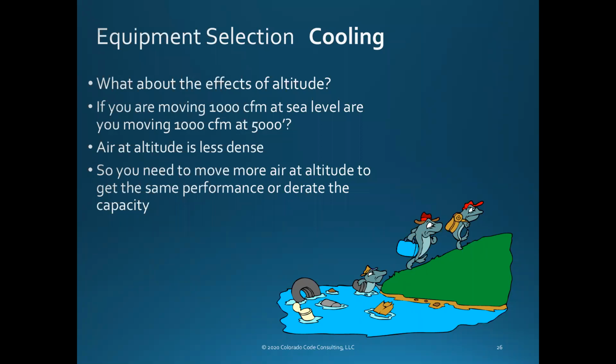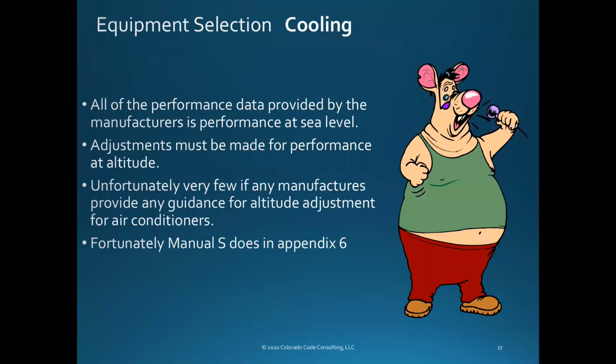Most of the designers I'm familiar with in Colorado and dry climates prefer to increase the airspeed. And why do you think that is, guys? Because we have a really low latent capacity and more sensible. Moving more air makes the coil warmer. It satisfies the air conditioning needs.